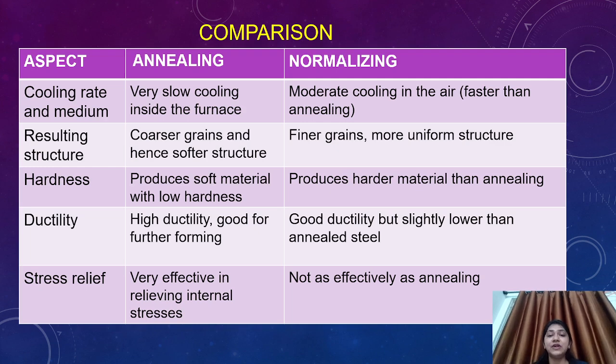Here in this slide we can see a clear comparison between annealing and normalizing, considering different aspects, like what is the cooling rate and medium, what is the resulting structure, what will be the hardness, what will be the ductility, and what will be the stress level.